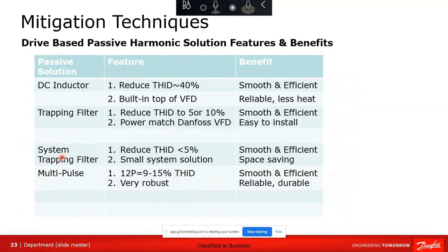I have to give that a caveat because I know there are some non-water wastewater people here. The Aqua drive, which is the water system drive, includes the DC link coil. That's the FC202 series. The automation drive, the FC302 series, includes the DC links. If customers in the audience are using the Danfoss micro drive, the low cost one that I think stops at 30 horsepower, that has no DC links. It's not designed for that. It's designed for shaft turner applications and things like that.